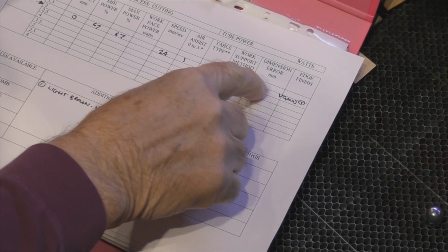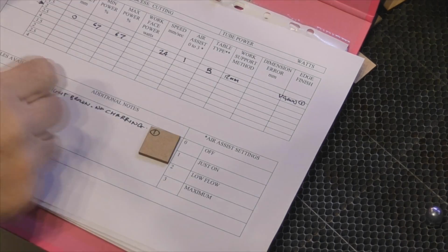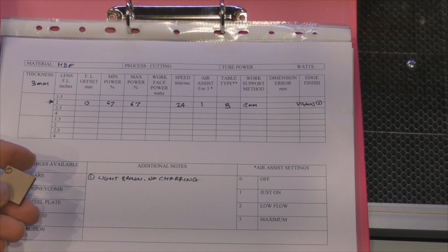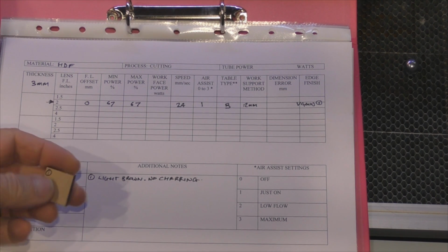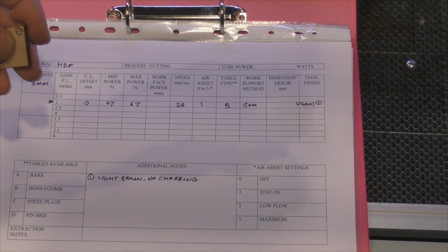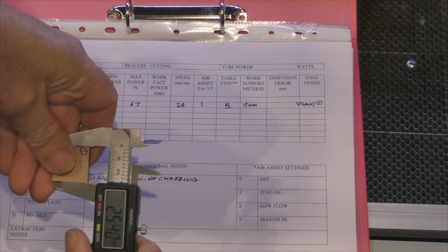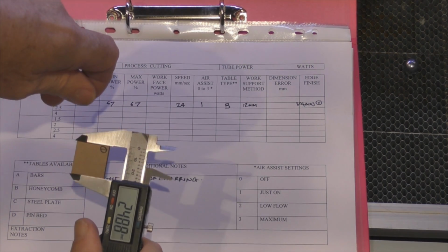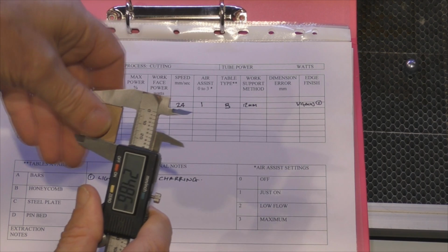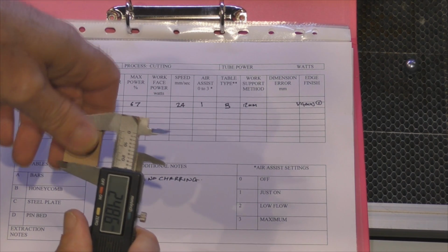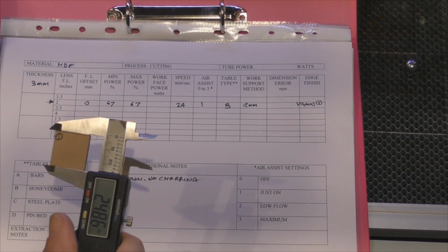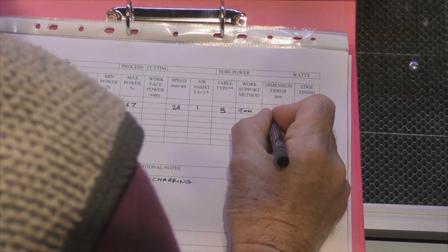Now, one thing we've missed 2 things out. Dimensional error. I thought I'd put a 40 by 40 program in there. When I measure this, or when I'm just about to measure it, I realise, hang on, that's not 40 by 40, that's probably 25 by 25, which is another program that I've got loaded in the machine there. Knowing that this was supposed to be 25 by 25 to start with, it's finished up at 24.88, say 24.9, 24.86. So on average, it's lost 0.15 minus